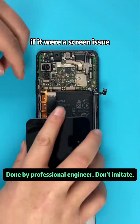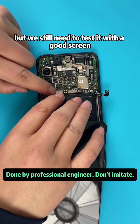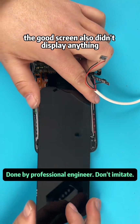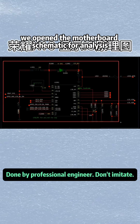If it were a screen issue, it probably wouldn't have been sent to us, but we still need to test it with a good screen to be sure. We connected the power meter, pressed the power button again. The good screen also didn't display anything, just as we expected. It's a motherboard problem. We opened the motherboard schematic for analysis.